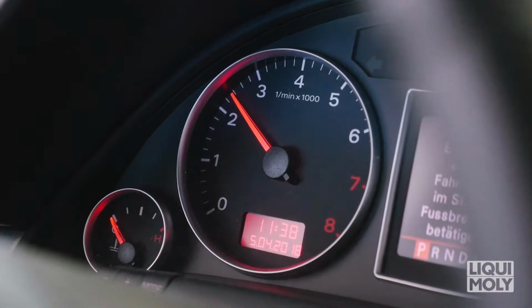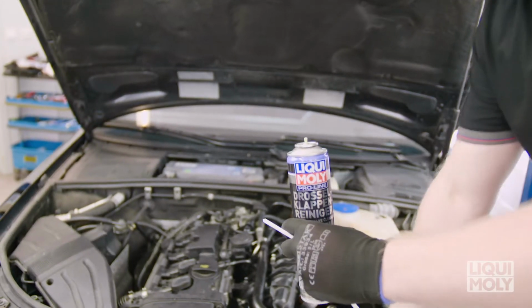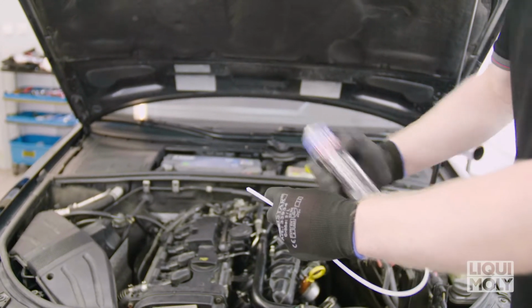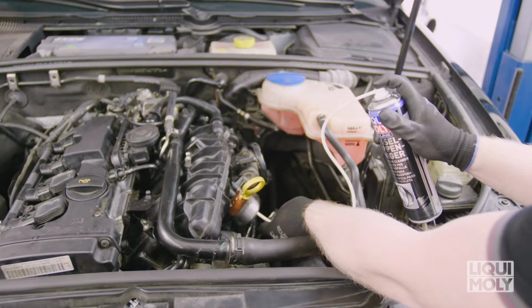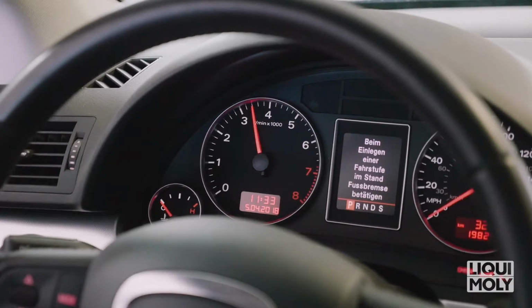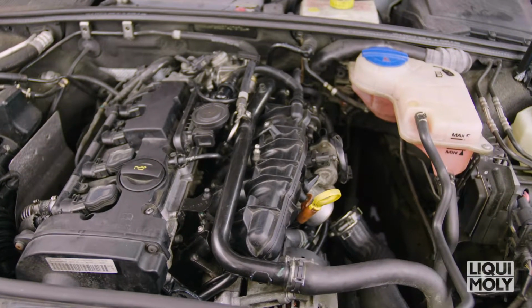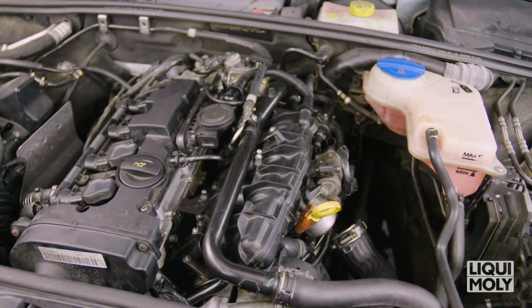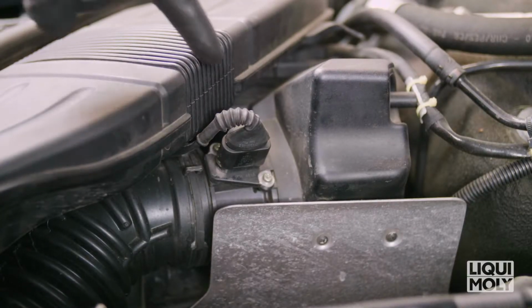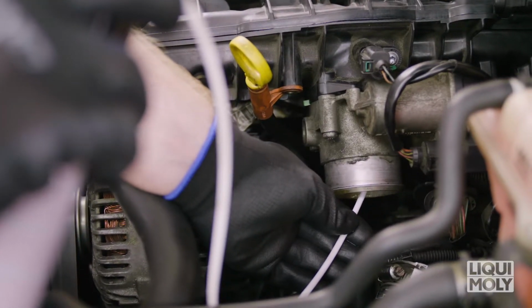While holding the engine at a steady 2000 RPM, spray the throttle valve cleaner into the throttle opening with the spray nozzle while making sure the engine RPM stays constant. If the engine speed fluctuates more than 1000 RPM during cleaning, stop spraying for as long as it takes until the engine speed recovers. Please note that the throttle valve cleaner fluid must not come into contact with the mass airflow sensor or with any painted surfaces.